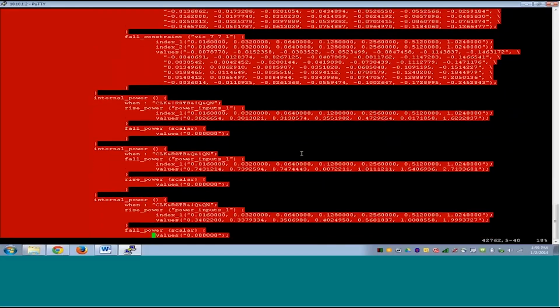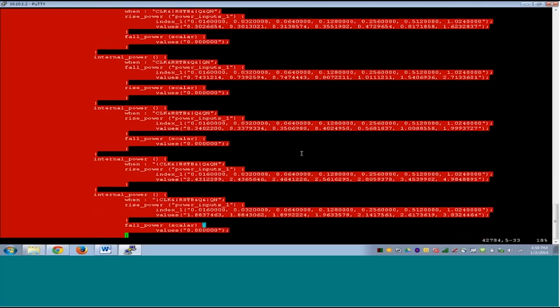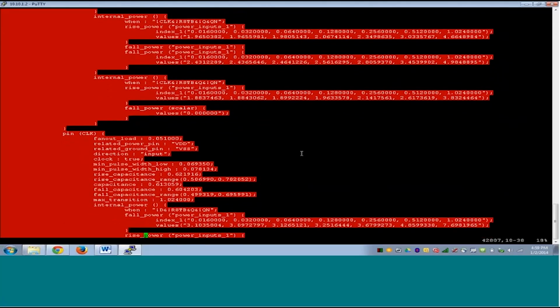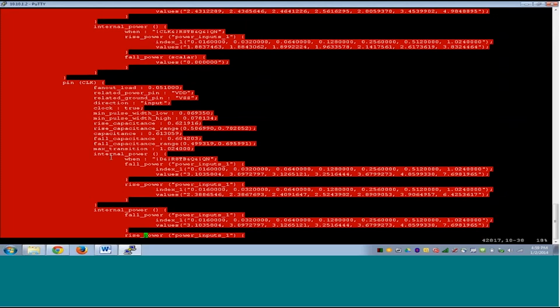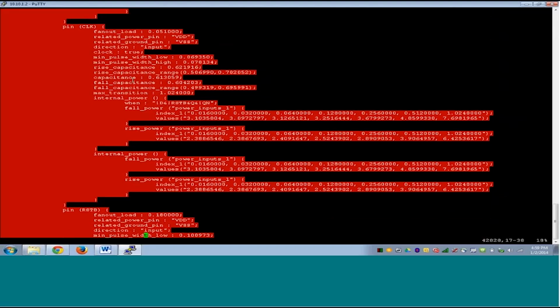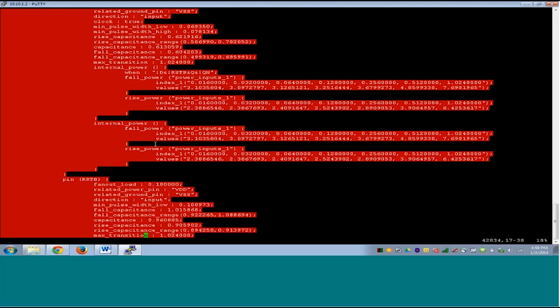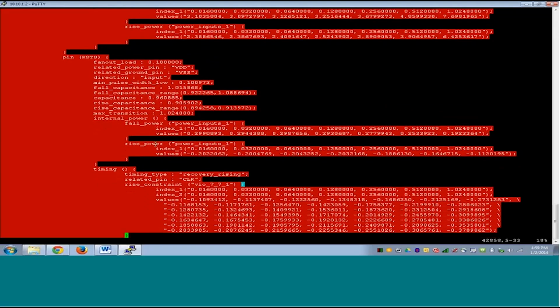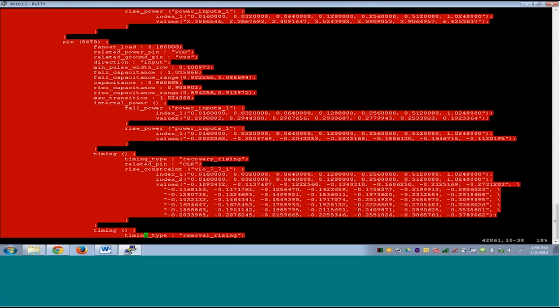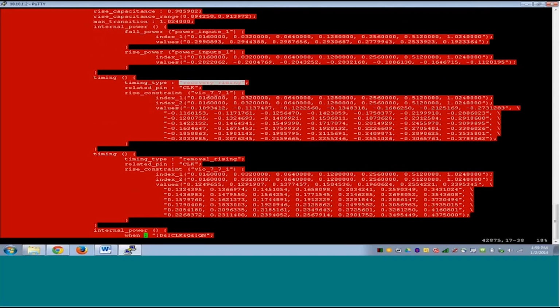Now let's go to the pin Q. So this is the pin CLK. Now DC knows from this clock thing that this is a clock pin of a flip flop. Again, clock does not have any timing parameters. It just has power parameters. There's a reset B pin. Now a reset B, which is asynchronous, will have a recovery and removal timing, similar to setup and hold. Recovery and removal.